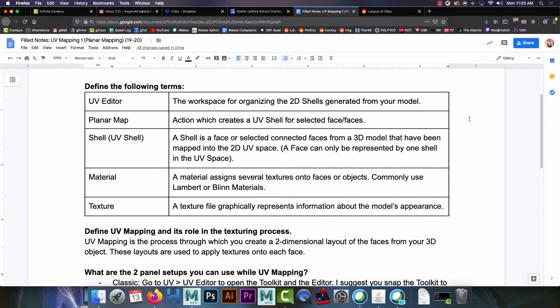Now, one of the things that probably flew by you guys, you didn't realize what the meaning of it was when we were looking at that Summoner's Rift video. He was using those big scanned rocks, and one of the things he touted as being really great about the rocks is that they only had 4 UV islands, as he called them. Basically, the UV mapping was done really well, so there are only 4 seams on the object, so it's not easy for people to tell where there are seams or cuts along our 3D object for the 2D shells.